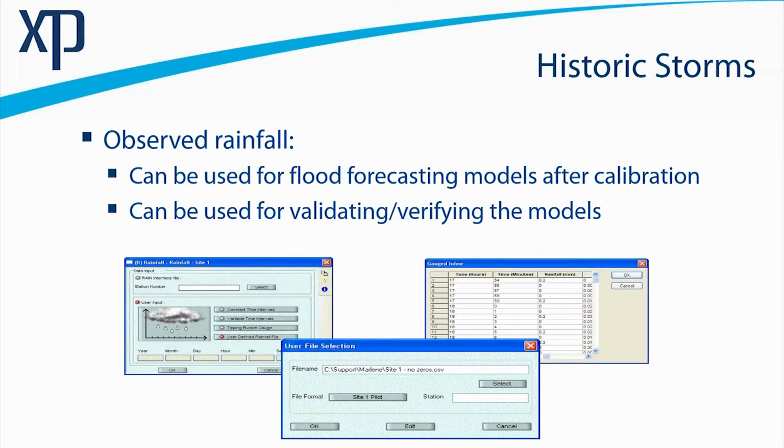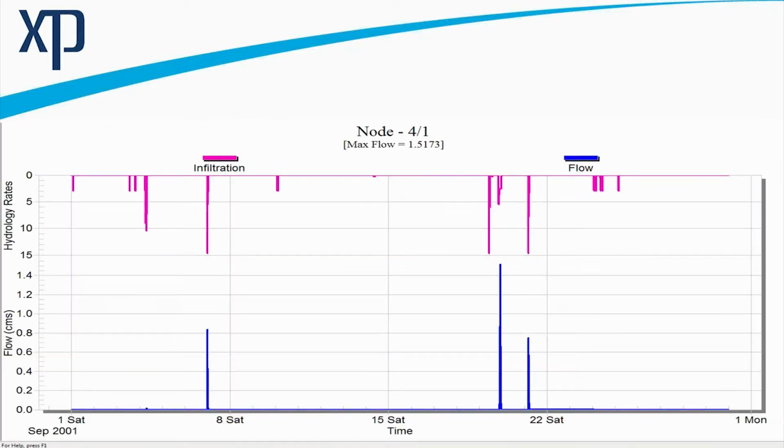We can feed in those rainfall values, apply infiltration procedures to that to define discharge from our catchments. And so what I've done here with a real rainfall set is applied some ongoing losses, and we can see that because of the potential for catchment infiltration, we don't actually have any runoff in response to these small events. But when we get into these larger events, we see spikes in our runoff record.